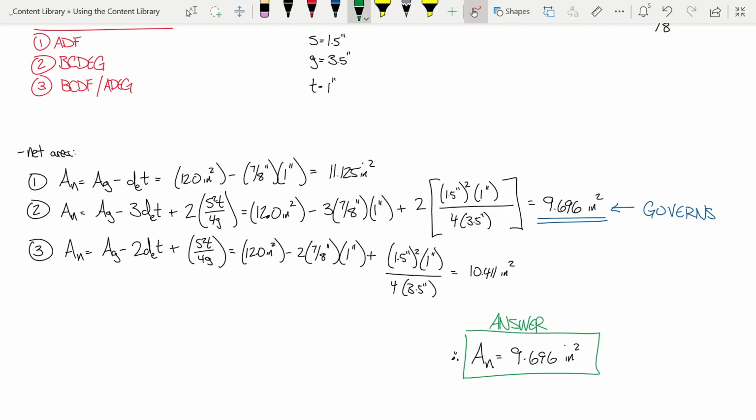Now, the way that we handle this is we break out our secret weapon of structural engineering, the samurai sword, or the lightsaber if you happen to be a sci-fi fan, and we turn this into a big old equivalent plate. And so we put that little nub down here, and now we have a staggered connection. But this distance and this distance are not the same. They're different because of the geometry, because you're turning that angle into a plate, okay?